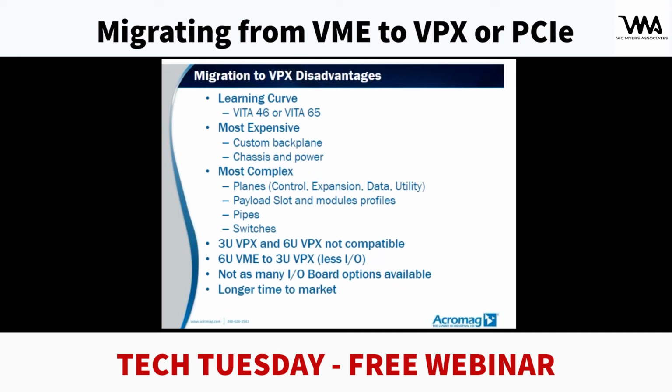And other disadvantages are that 3U VPX and 6U VPX are not compatible. You have less I/O when you migrate from 6U VME to 3U VPX. And in the 3U VPX and 6U VPX world, there's not as many I/O boards available. Typically, you're going to end up using some type of carrier board in an XMC, PMC, or Acromag module to get the I/O that you require in your VPX system. And finally, one of the disadvantages is that it's longer time to market for all the reasons above.